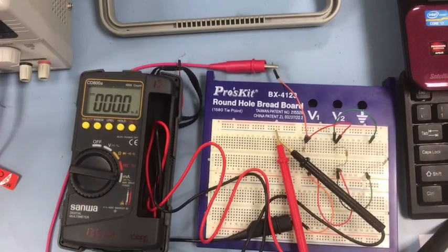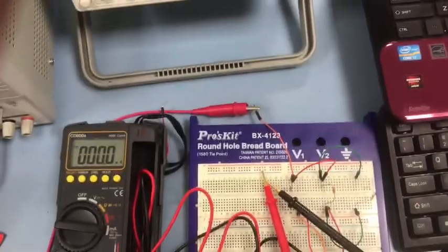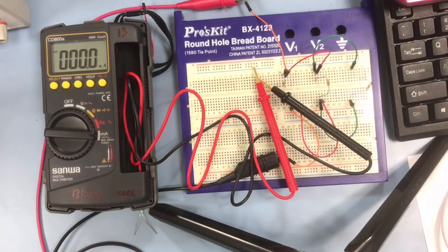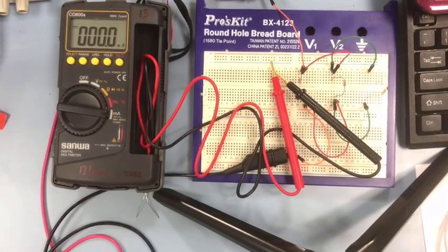Okay. So basically the total current, the overall current should be, if you understand the concept of current in parallel circuit, I total is equal to I1 plus I2 plus I3. So you can see in experiment data here, it exceeds 140.4 that we measured in AB. Okay, I think we can do the measurement again.